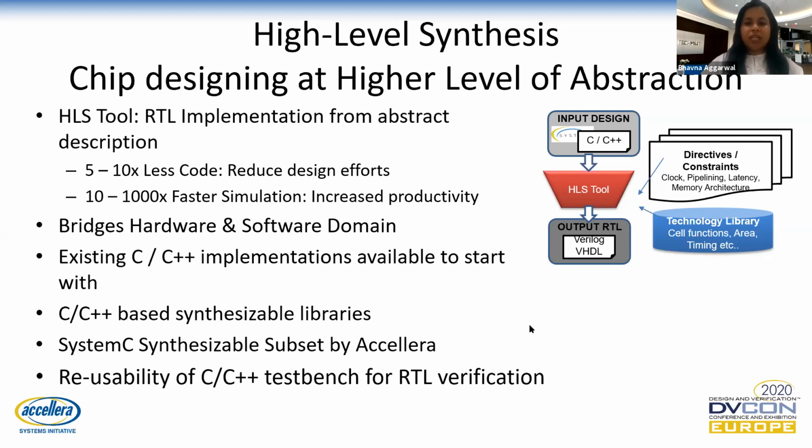The designer typically develops the behavior and the interconnect protocol. HLS tools transform the untimed or partially timed functionality into fully timed RTL implementation as well as create a cycle-accurate hardware module.